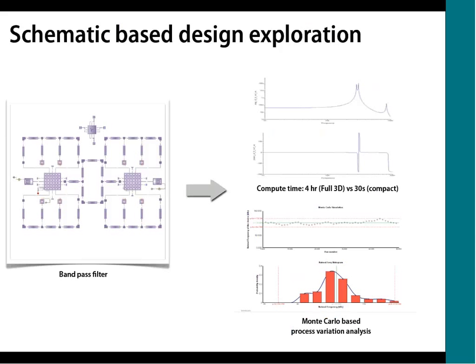And like I said, the advantage of this tool is that these behavioral type simulations can run very quickly, for example, in just a few minutes, whereas with a full finite element simulation, if you needed to do, say, a full dynamic simulation, it might take several hours to run. And even though this is a much faster simulation, the accuracy is still very good, usually within 5% or so of the full finite element simulation.